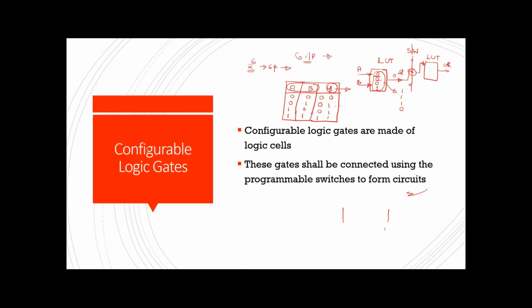Consider the amount of time required to develop that, and how many hundreds of engineers work on a single chip. If you make any mistake, it's not correctable there. You have to go through a lot of verification effort, physical design, STA, CDC, linting, everything. You have to go through the proper flow and make sure there is not even a single mistake in that IC. When you go to production, if there is any mistake, everything has to be refabricated in the chip. You cannot just correct it like we do in FPGA.